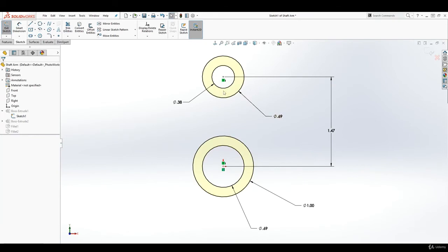Let's say you've modeled your part. I've made this part now, and let's say I decide that this dimension is different now, and I just want to change it. So what parametric means is the dimensions and the relations allow us to go back into the sketch we've already made and easily change it, and it will be automatically applied to our part. So I'll just show you.